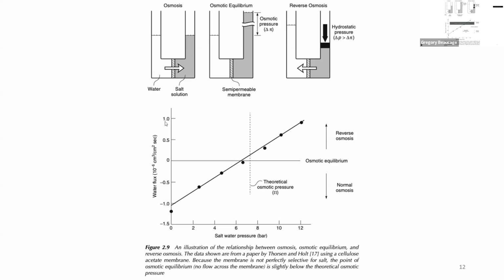Yeah. So basically, you have a membrane, cellulose acetate, and it's going to be a membrane like I showed you, where it's been made so it's got straight pores and then a thin film that's like a micron thick or less, right, of the cellulose acetate, and it's going to be wound into a canister, like a rolled film, and then you're going to pump in one side, and the film separates two channels, even though they're all tightly packed together, right? And it's going to just pump through, force it through. So it's going to do this operation.